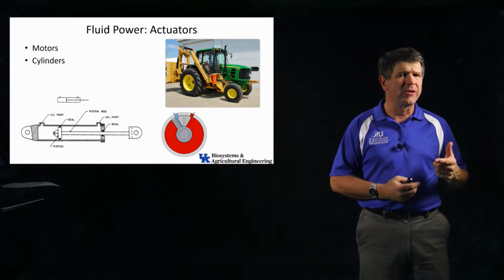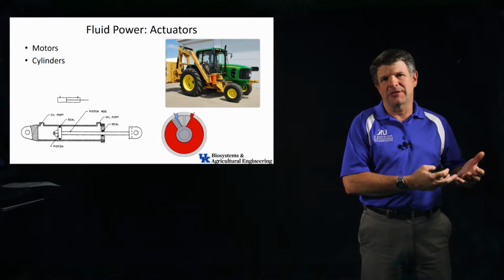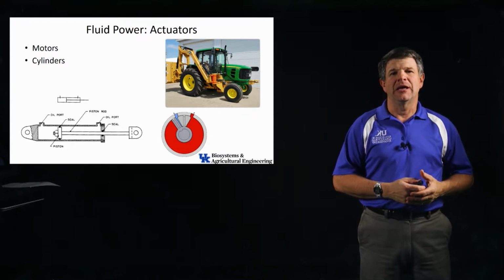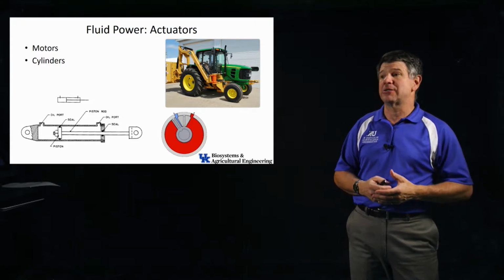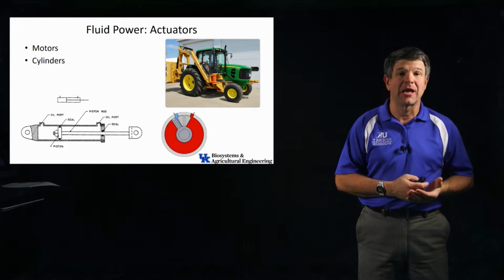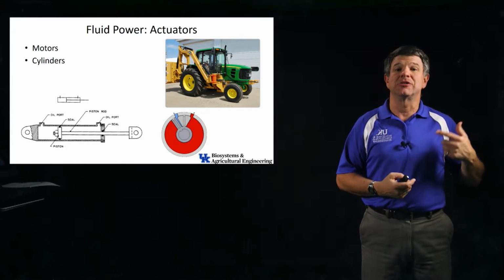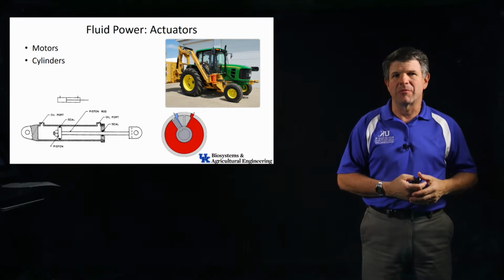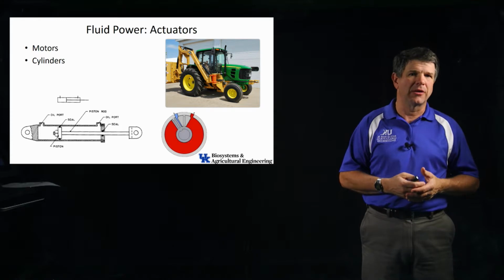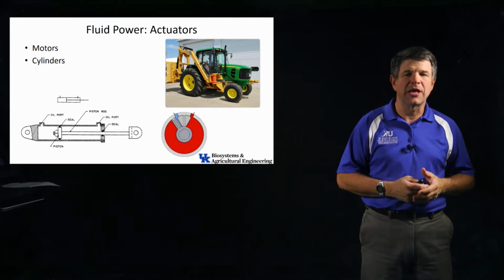And again, primarily we're looking at either rotational power to rotate some machine, or linear power where we move something linearly. And we've already talked about the motors, so I won't spend any time with them here. They're basically the same thing as pumps. Functionally, they're the same. The efficiencies go on the opposite side, so you have to remember that, because the input to a motor is the fluid power and the output's the mechanical, whereas for the pump, the input is the mechanical and the output is the fluid. So just keep that in mind.